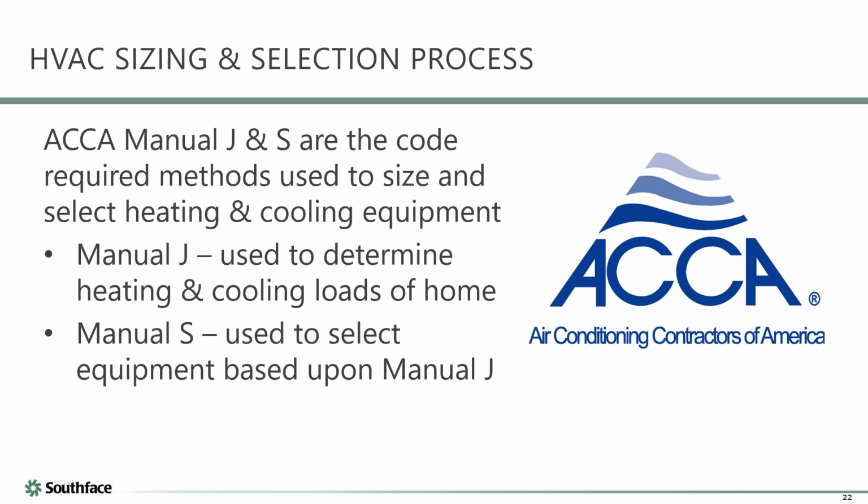And heating is pretty easy, and there's a lot of wiggle room on the sizing on heating. You want to be at least as big as the heating load. Cooling is a little more tricky, and there's a slightly different set of rules if you're an air conditioner or if you're a heat pump. You can essentially upsize a heat pump a little bit more than a straight across-the-board air conditioner.